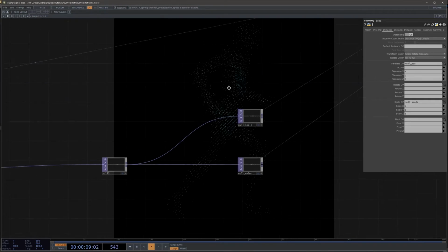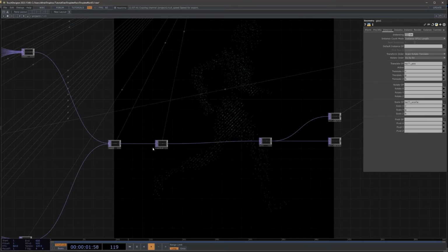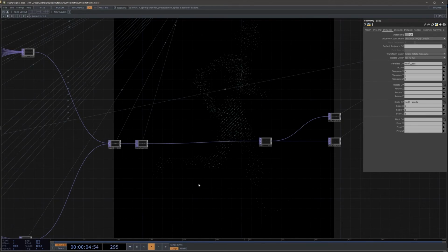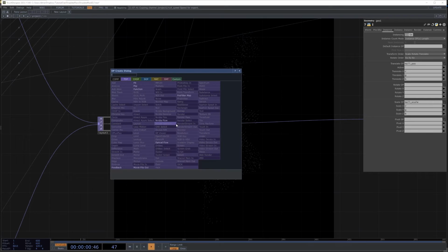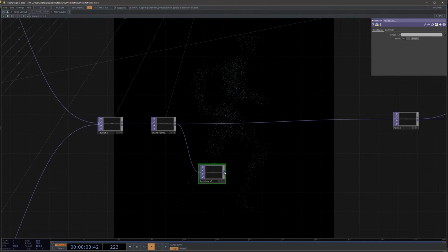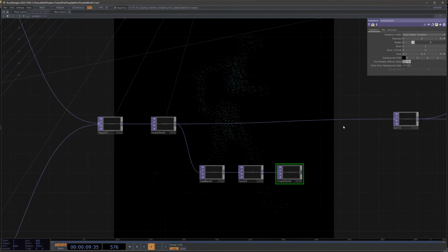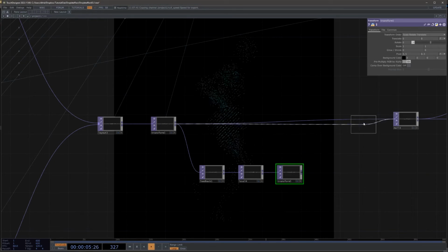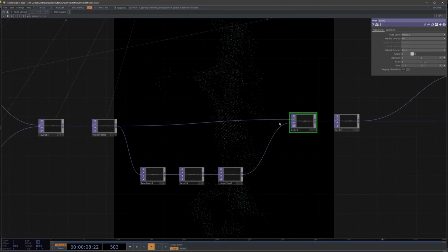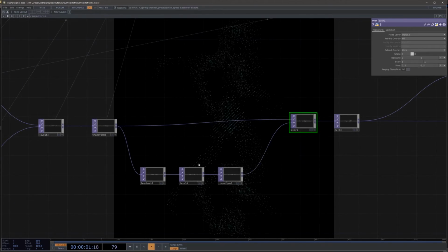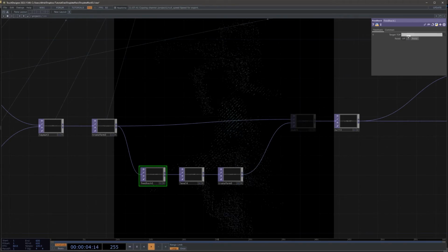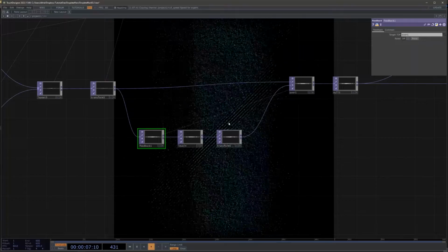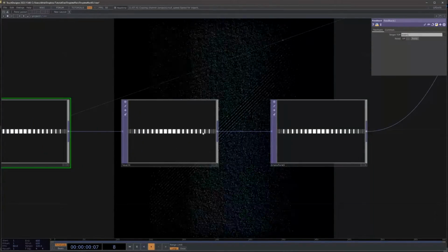So now to really have a falling effect, we can even create a feedback system to have some feedback effect of a falling rain. So after the transform, I'm going to insert feedback, connect it to a level, then to a transform, and we are going to composite with an over operator. So be careful to choose the transform as the first entry and feedback as the second, and into the feedback I'm going to choose the target top over. And so we can see it's kind of falling and creating too much feedback.